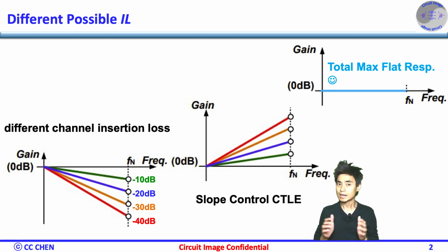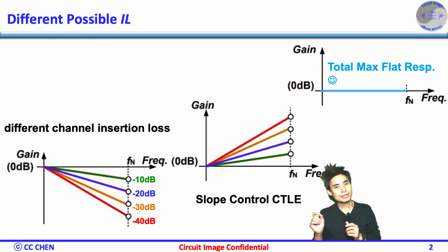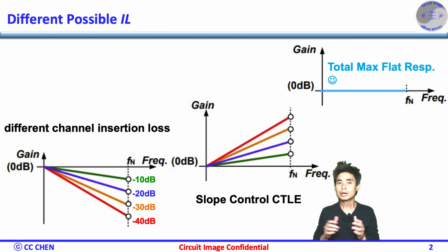But we need to design the ADC resolution requirements for the target insertion loss, since we are also working on the highest data rate up to 224 gigabit per second. The ADC could be power hungry if we also design a high resolution ADC. How do we consider it?